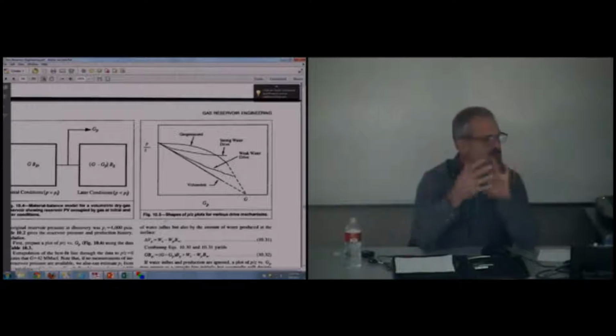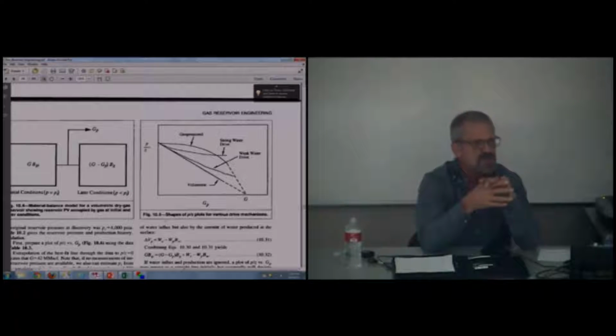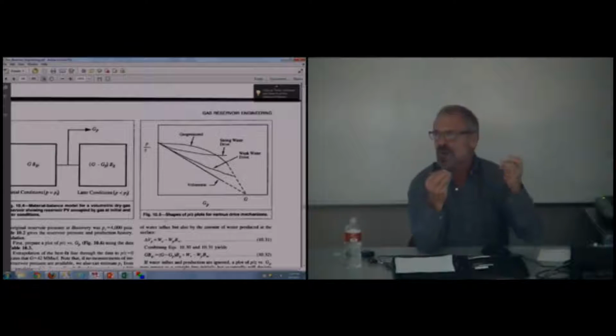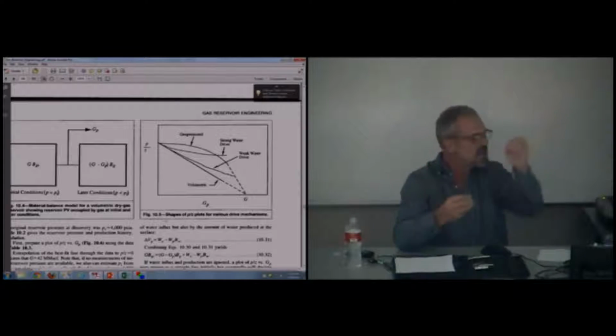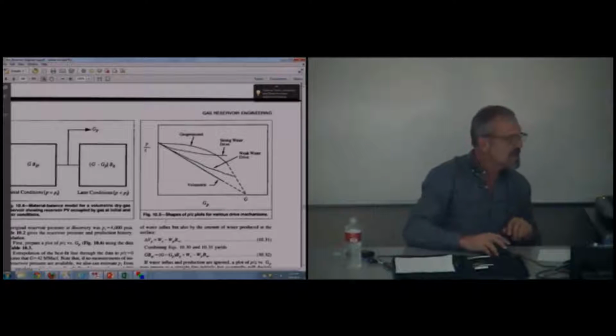But with the piston, because we knew the volume and the pressure, we were able to calculate Z. Here, we're calculating Z from fluid properties. We know the pressure drop is from 5,000 to 300. So now there's a linear relationship. From P over Z to P over Z at abandonment, 1 minus that is the recovery. Okay, so let's do that.